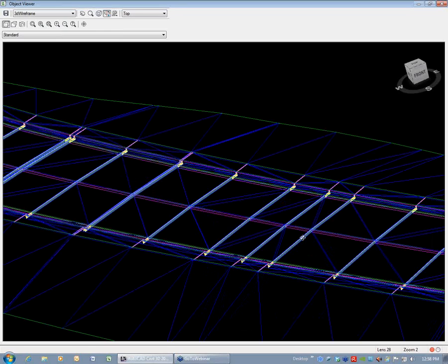So you can kind of tell what's happening, right? Each one of the sections is just connecting it with strings or 3D polylines or feature lines, if you want to call it, to create that structure. Obviously, if you want it to be exact, you need more feature lines or more frequency in there. There's a lot that we can do.